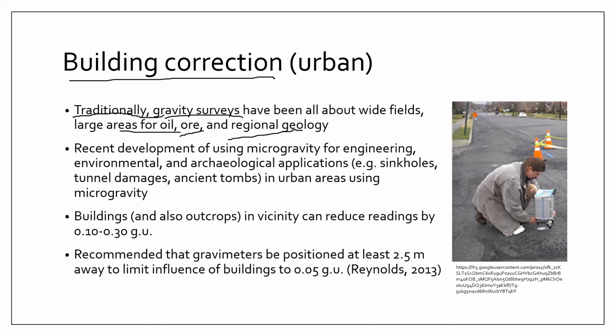It's just a recent development that people are starting to use microgravity for engineering, environmental, and archaeological applications. Okay, for example, looking for sinkholes, looking at tunnel damages, looking for ancient tombs in urban areas.